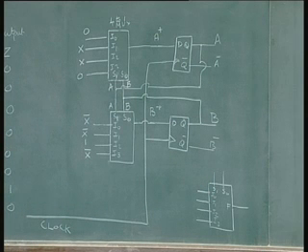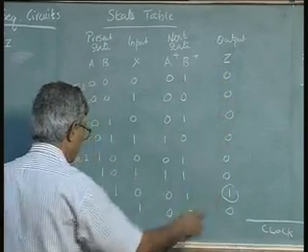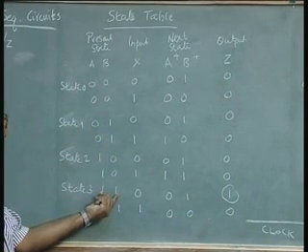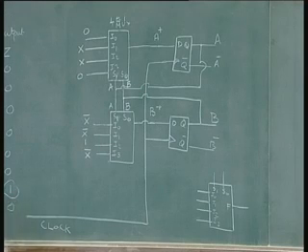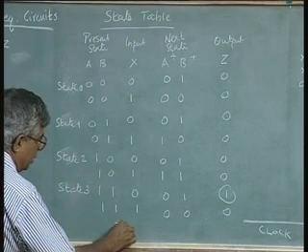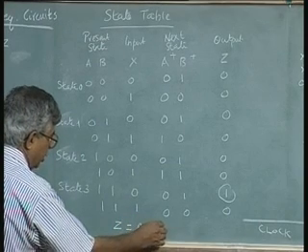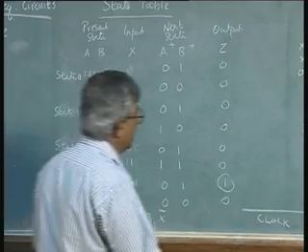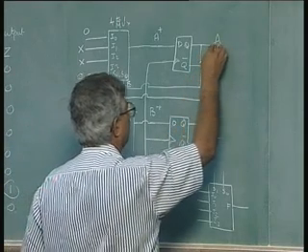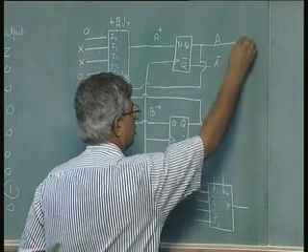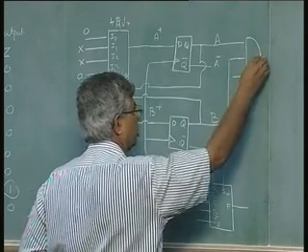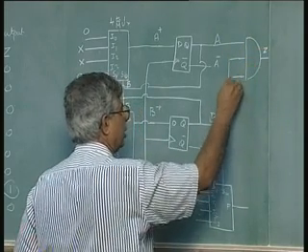Now, the output side, there is only one output of 1 and all others are 0. That output comes when the input is 0 1 1 with an input 0. So, output Z can be written as AB x bar, correct. Since x bar is available here, you put AB and x bar, and this is my output C.